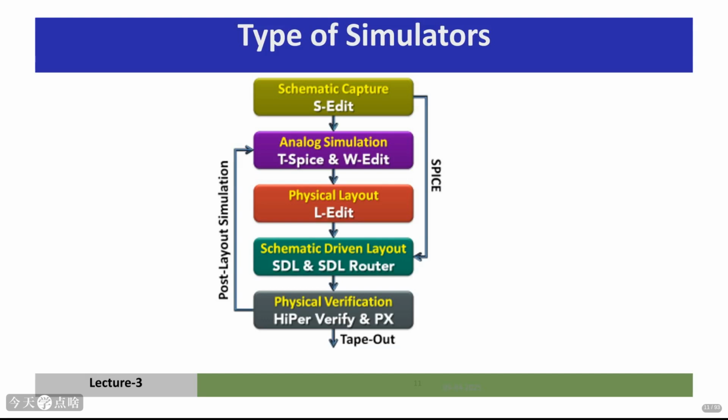Here's a typical workflow you might see in practice. You start with a schematic, a drawing of your circuit. Then you use a simulator like T-Spice to analyze its behavior. Next, you create the physical layout using tools like L-Edit. Crucially, you verify this layout against design rules using tools like Hyper-Verify.